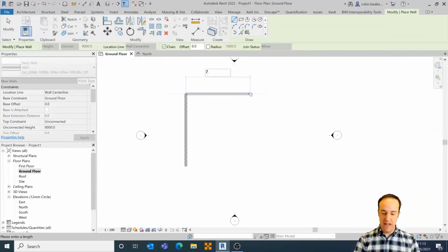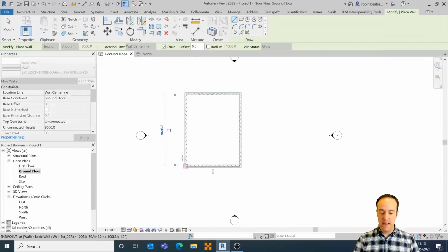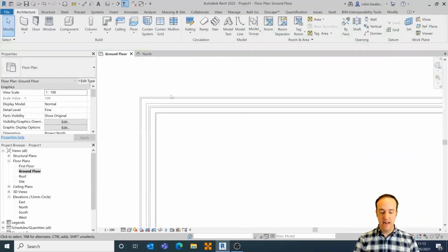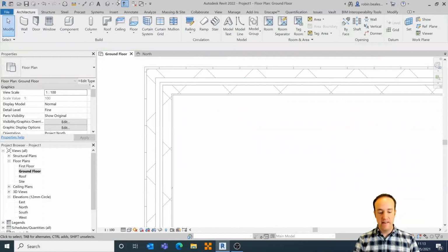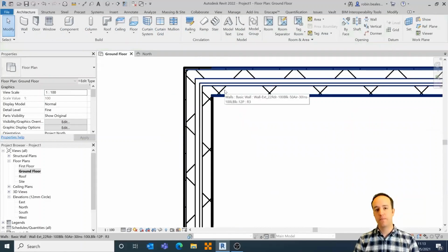Unlike in a 2D application, for example, where you might only have a polyline or a standard line here, what Revit's doing in this particular case is it's creating a fully detailed and fully defined wall. Now, you can see that particular wall has certain line styles or line thicknesses. Typically in a 2D workflow, these would be controlled using your layers from the template. Revit has a similar setup, where you define line types, line styles, and different weights. But generally speaking, it's controlled by your scale.